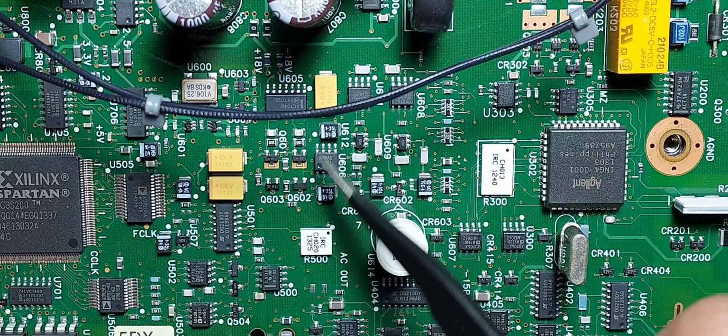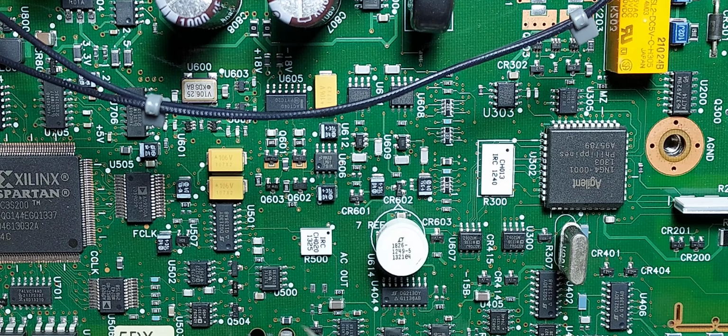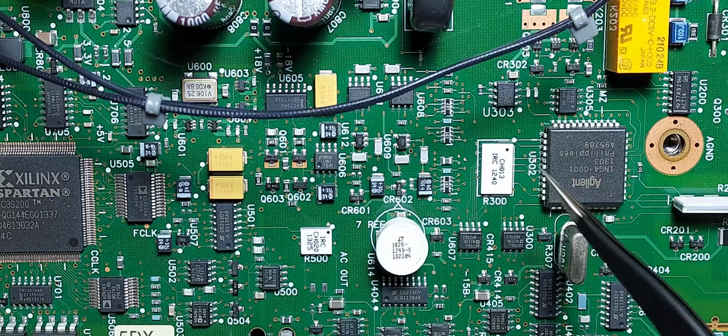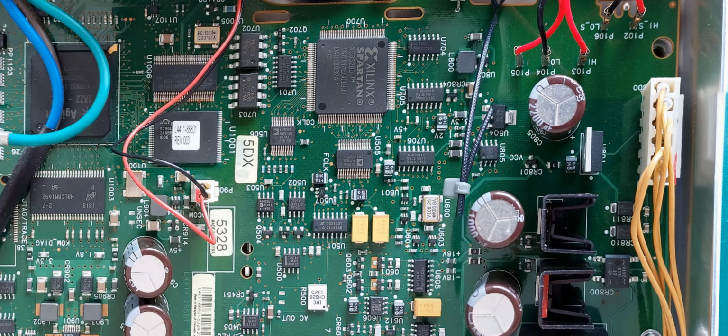Here's the damp switch, which feeds into a resistor network, which in turn feeds the current flowing through it into the integrator. Surprisingly, the helper op-amp from the DAC patent is missing on the actual board. The integrator capacitor looks to be a commercial off-the-shelf C0G. The coarse and fine ADCs feed directly into the Xilinx FPGA that forms the brains behind this operation.